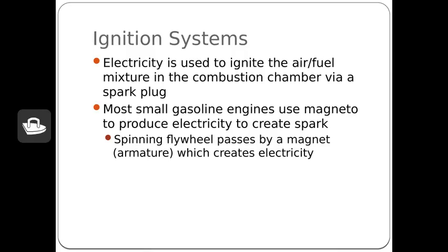Older Briggs & Stratton specific engines, like pre-1980s, you might run into one at some point that has that points and condenser. They can be fixed and they can be used, but Briggs makes a very handy retrofit kit to modernize the ignition system. And once you do that, you pretty much minimize the risk of failure in the electrical system once you get rid of the points and condensers.